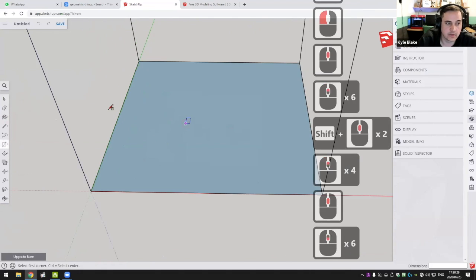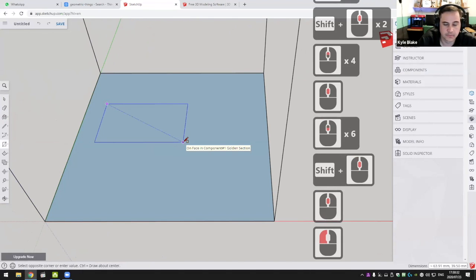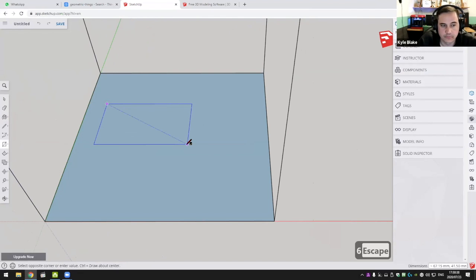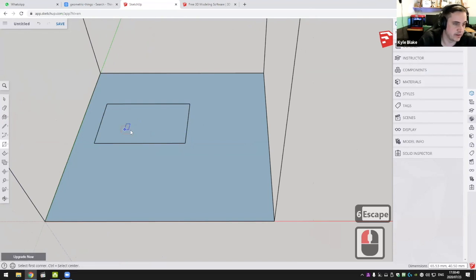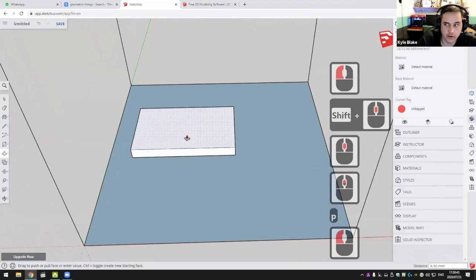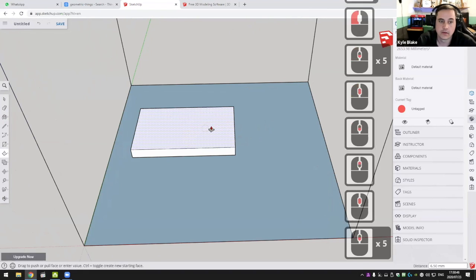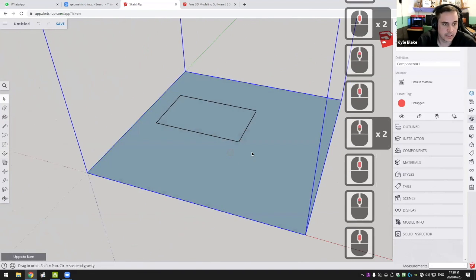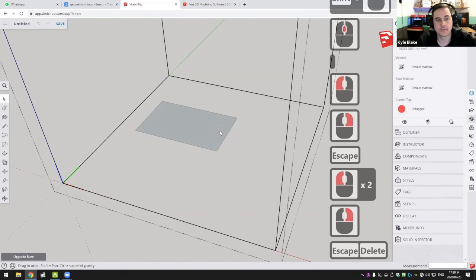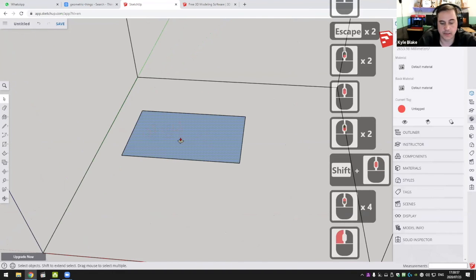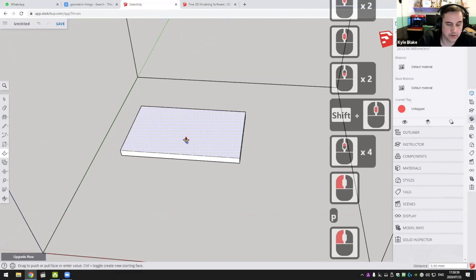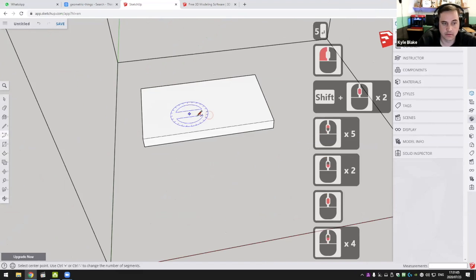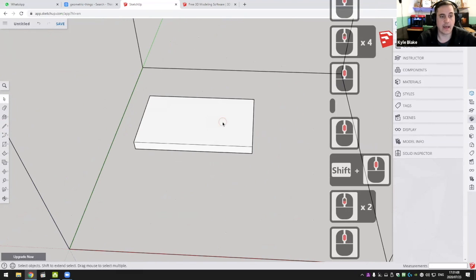So we can say, let's start with a simple name tag. Again, the rectangle. 65 by 40. And then we can pull this face up. They do overlap now, so they are a little bit harder to see. You can go and delete the original face, but you should see something like this now. So we can pull this up, let's say 5 mils. We can now add text to this.